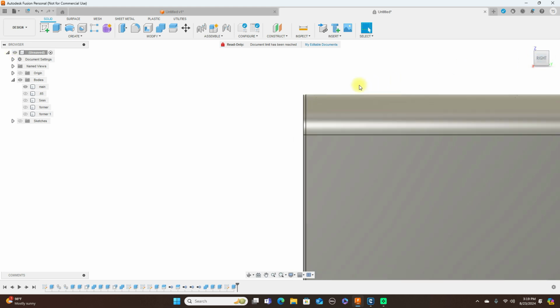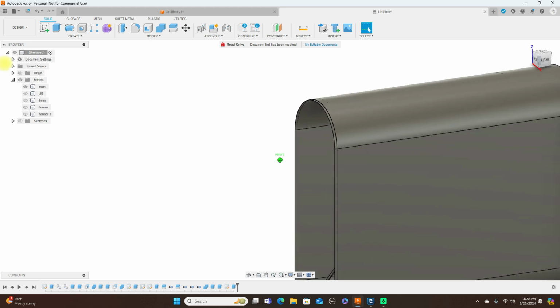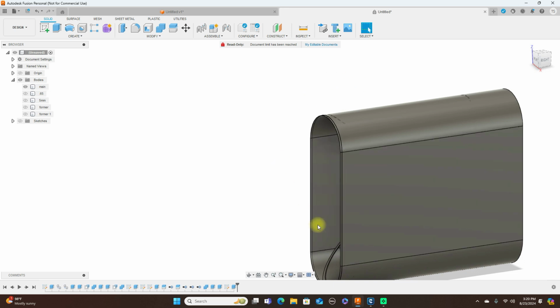And like I said, to do that, you just extrude this, create a sketch on this plane, offset the thickness of your printer nozzle, which was 0.4, and then you just do an extrude cut and just move it back. And that's how you get the little offset. So the other fuselage part will just slide onto here.